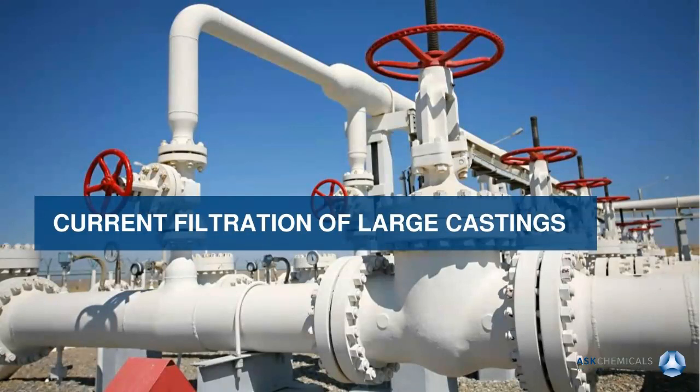The ideal case would be the placement of one filter, or let me say filtration system, at each ingate, and this should always be positioned as close as possible to the ingate to use the effects of the ceramic foam filter fully and completely. The manufacturing of filters meeting the required size in a single piece is technically challenging, bringing additional risk and failing to be economically feasible.